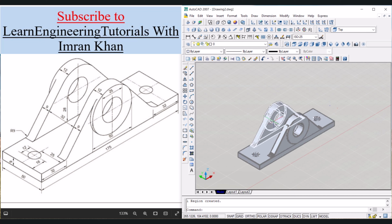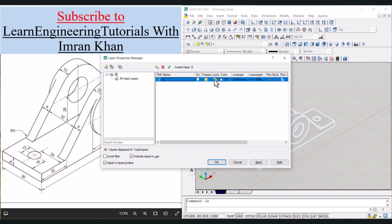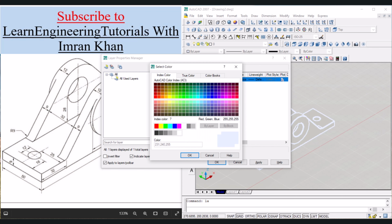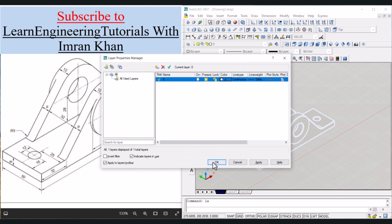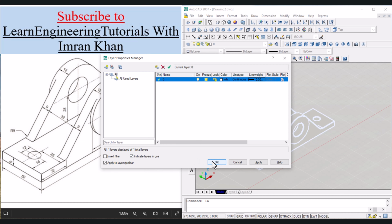We want to union each component, so click on union icon, select this object, and this object, press enter. Now click on this 3D hidden visual style, write LA, enter, select the color to be white, click on OK, select the line weight to be 0.3, click on OK, and then click on OK again.